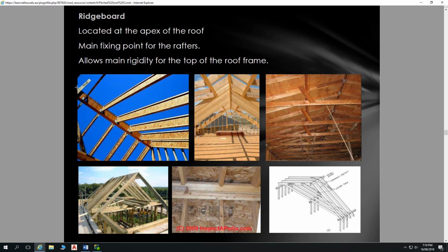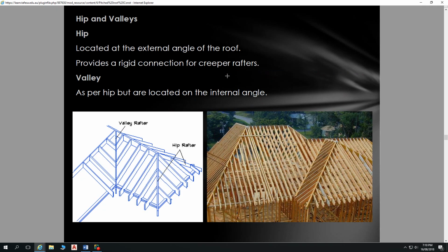Ridge boards, so that's the piece of timber that goes across there, and the size of our ridge is specified in the timber framing code as being, now this is just off the top of my head, don't quote me, 50 millimeters deeper than the plumb cut of the rafter. So our rafters here, the plumb cut, that's that cut at the end. Our ridge needs to be 50 millimeters deeper than that, or thereabouts. It relates to the size of the plumb cut of the rafter.